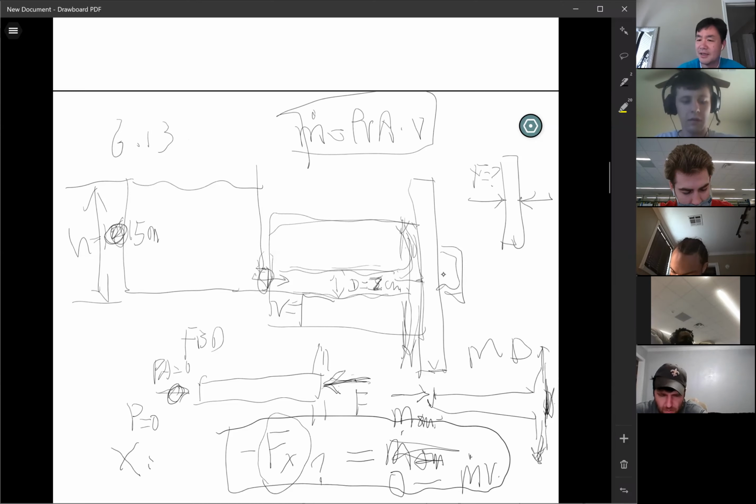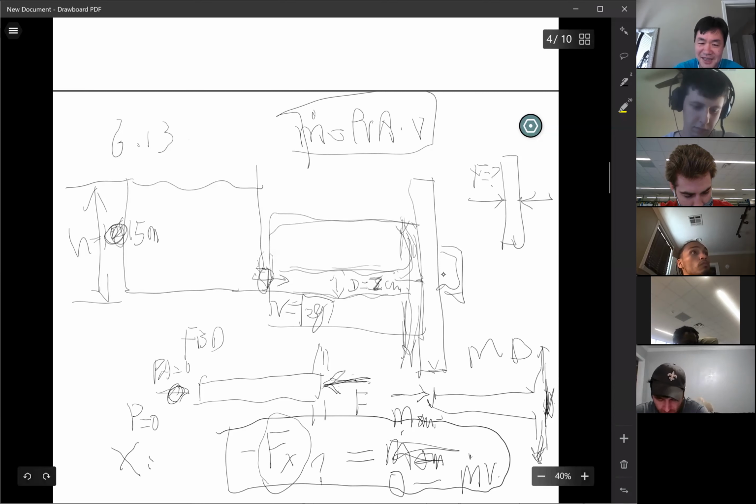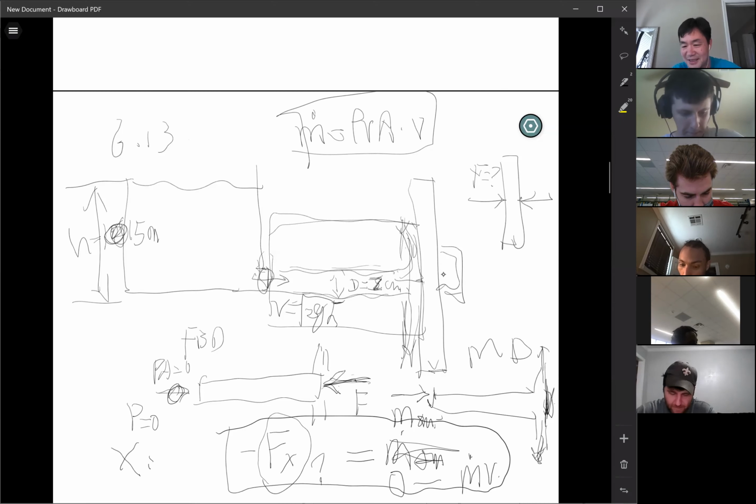You forgot how to calculate the outlet velocity of the tank when the water is going out? You use Bernoulli on it? Yes, use Bernoulli. Can you memorize that outlet velocity? V equals the square root of what? 2gh. That's right. Come on, you can memorize it, right? Do you know h here?